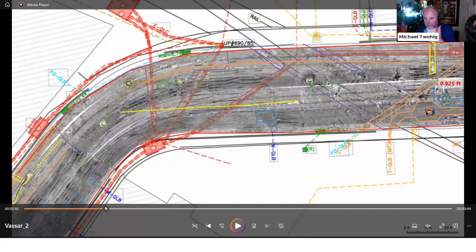The other part that's problematic is you can see down at the bottom, again, there's fiber optic that we have and there's communication. The problem with a lot of these, Kent, is that for years, the telecoms decided they didn't want to put a trace wire inside these systems. So if you're out there with an RD or a Metrotech, you might as well go play cricket or baseball with it because you're not tracing that.